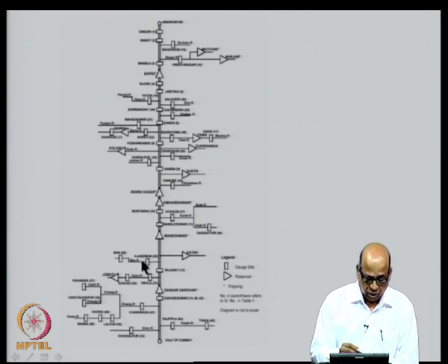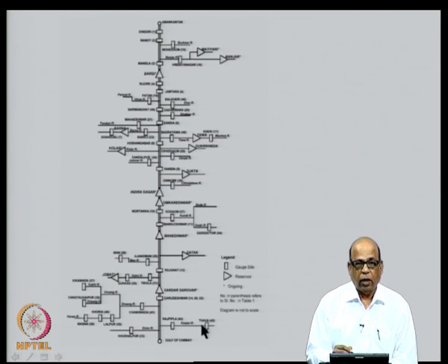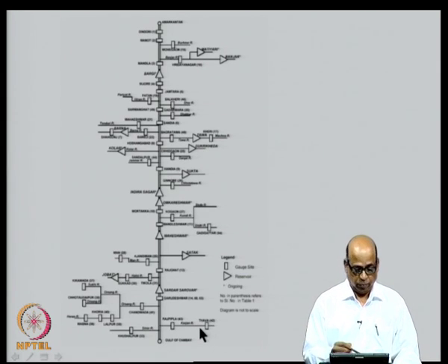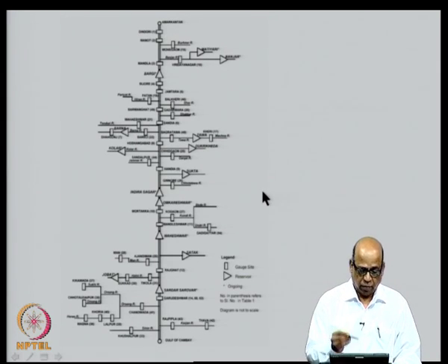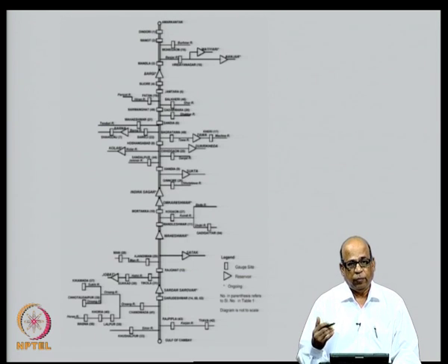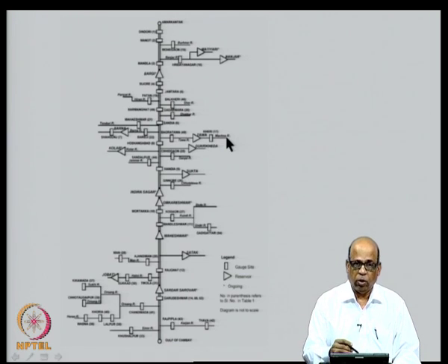And these rectangular boxes that you see here are in fact the gauge locations. So, there are a large number of gauges at which the data is available. The first exercise that we do in such large systems is to check the consistency of the data with respect to each other. That is consistency of the data at a particular gauge with respect to the gauges in the surrounding region.